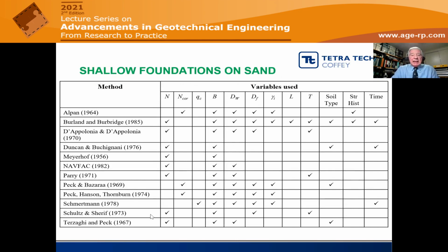Here's a listing, and again, I won't go through these, of various methods of estimating settlements of foundations on sand. Many of these are based on SPTs. A lot of these are from the earlier days of our profession. Some of the more refined methods use CPT, particularly Schmertmann, and then others use various other parameters or refinements.